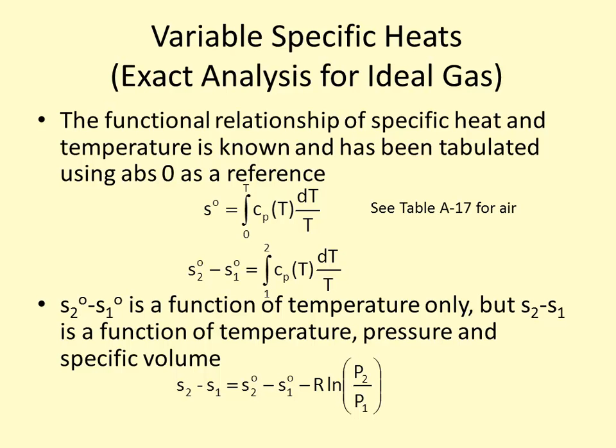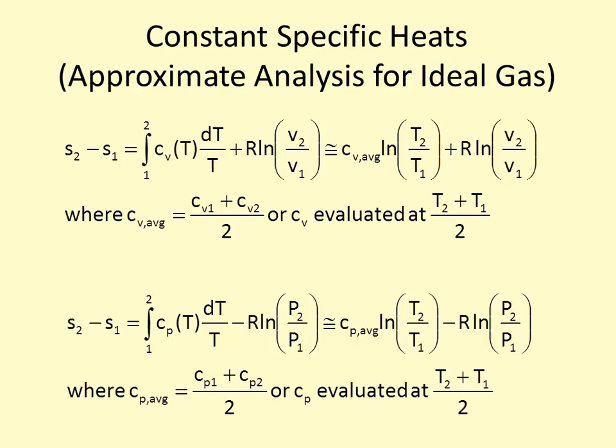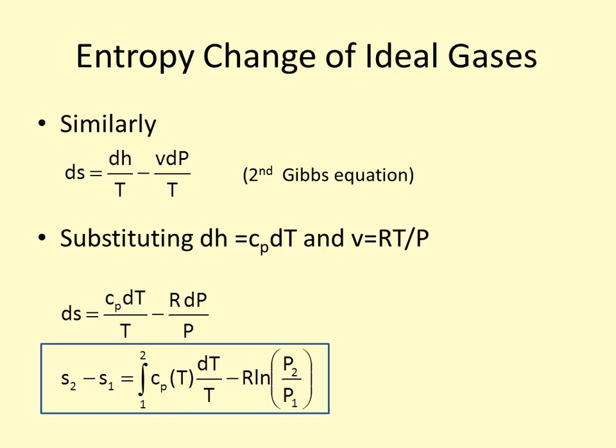Okay, so you'll see the ideal gas properties of air. We have the temperature in Kelvin, enthalpy, which is a function of temperature only, this reference pressure, which we'll get to later, internal energy, and then this S superscript 0. That is our reference entropy, a function of temperature only, and it's calculated using the specific heat as it varies with temperature, which is a known formula. Because it's complicated and we don't want to calculate it every time, it's been tabulated for us, and we can use this relationship substituting into this equation here.